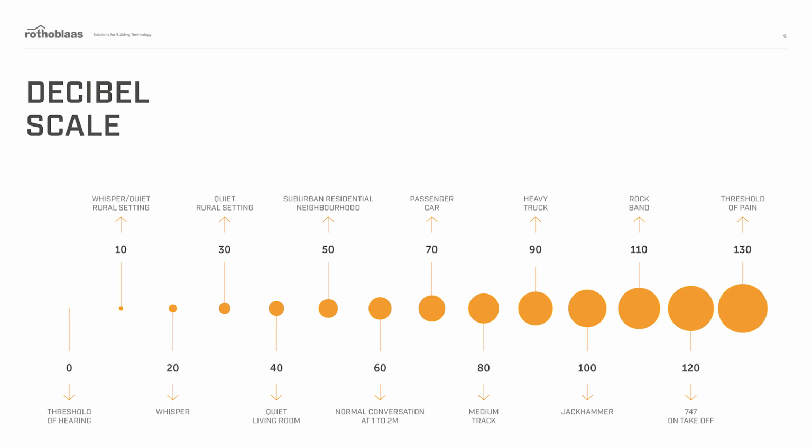0 decibels is the quietest sound audible to a healthy human ear. From there, every increase of 3 decibels represents a doubling of acoustic power. The relative loudness that we perceive is a subjective psychological phenomenon, not something that can be objectively measured. Most of us perceive one sound to be twice as loud as another when they're about 10 decibels apart. For instance, a 60 decibel air conditioner will sound twice as loud as a 50 decibel fridge.